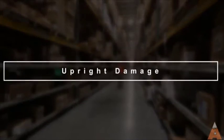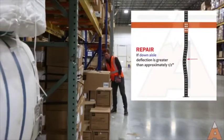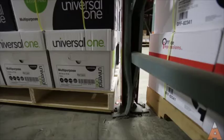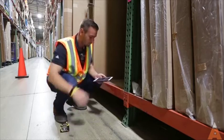When recording upright damage, be sure to note any deflection greater than a ½ inch from front to back and down aisle. Indicate if the steel is torn and where the damage resides within the upright. If there is a separation between the column and seismic backer, note that is damaged and check to see if the frame is plumb front to back and side to side.